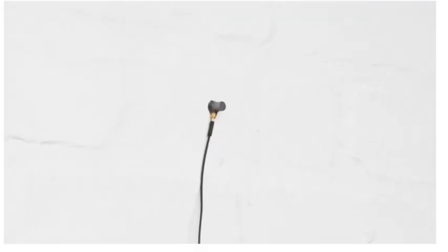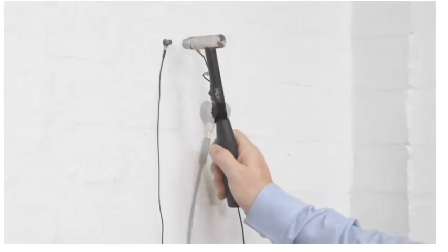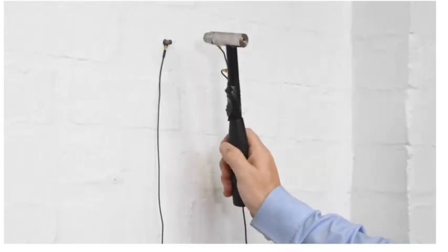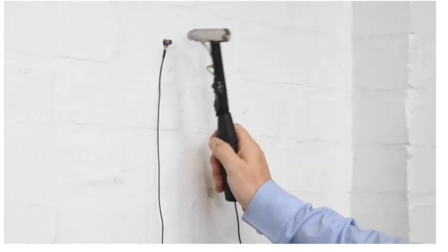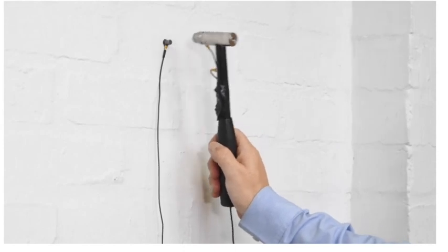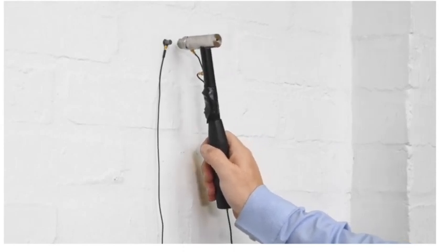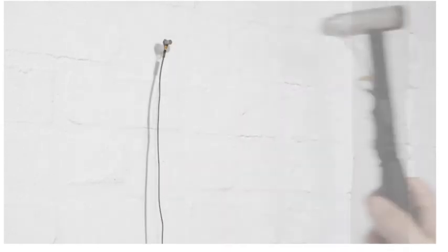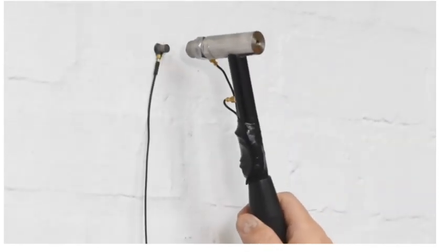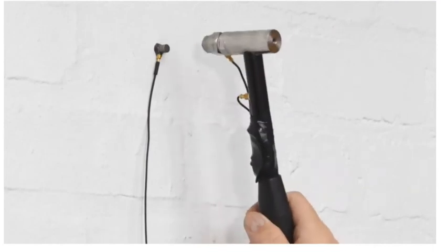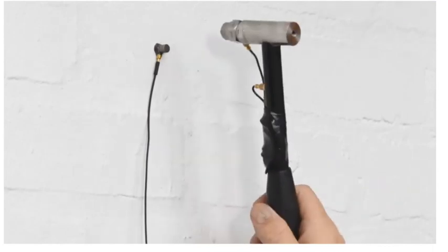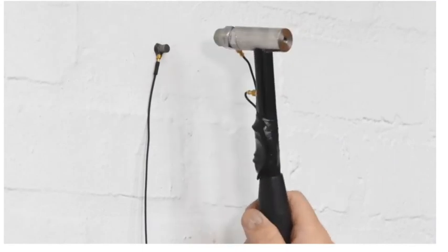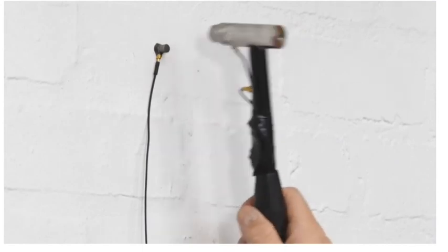So you've got an accelerometer on a brick wall fixed via beeswax. You can also use super glue if you don't have beeswax, and an instrumented hammer tapping right next to the accelerometer to get the driving point or the point mobility. You may need to do 3 to 4 hits to get an averaged mobility at that point.